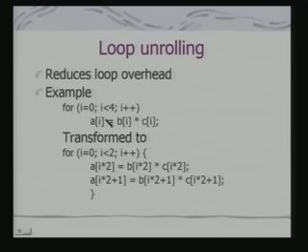So, effectively I can do the same computation using fewer loop iterations. So, the loop overhead goes down. Now, we can say that you have introduced this many multiplications, but if you remember the ARM architecture, these are not really multiplications; they can be done as part of the same instruction itself because of the barrel shifter. So, I get a much better optimized code for the loop.